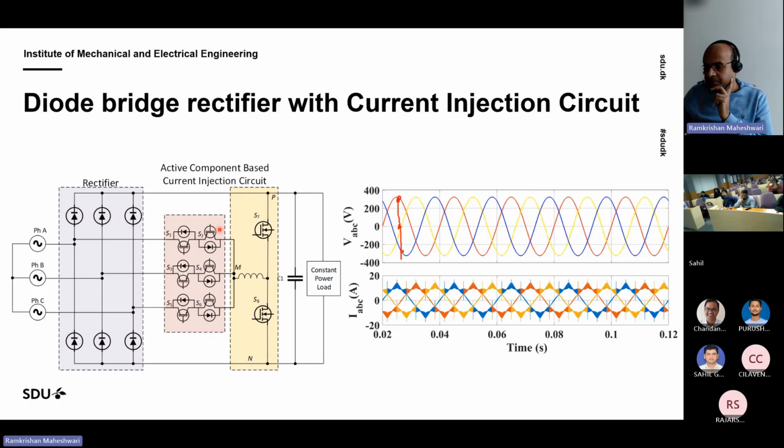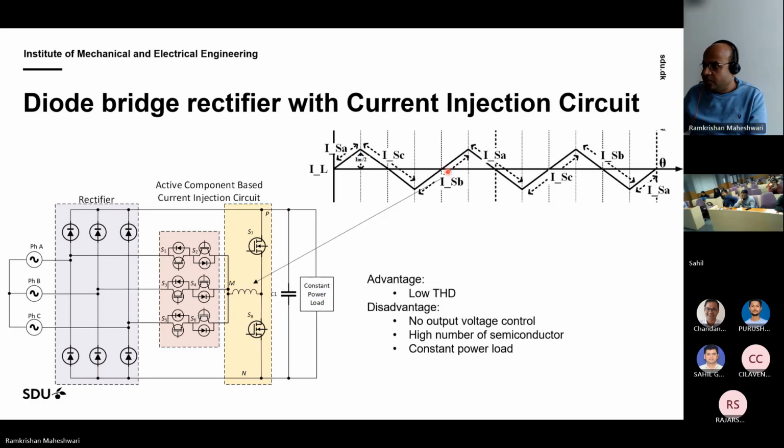Okay. So this is a good advantage here, but the inductor current waveform is something like this, which is 150 Hertz, which is not DC. So we need to have a high bandwidth current control here as well. And that is why we go for a silicon carbide based system with high switching frequency, high sampling, and high current control bandwidth.